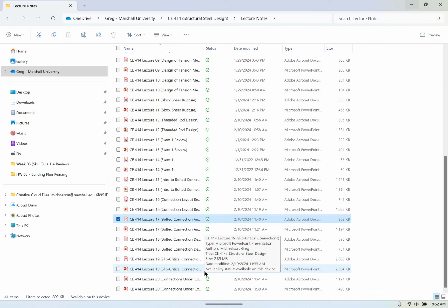You might look at this all said and done, and then find that your plate doesn't have as much net section fracture capacity or block shear rupture capacity or anything like that, in which case you might need to iterate further. You're actually right. So you stole something I was going to talk about on Wednesday.